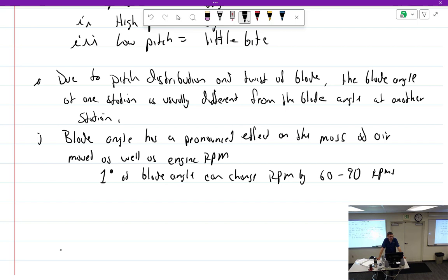It has to be in the chocks and blocked. So you'll actually look at the type certificate data sheet. That's where it's going to say it. It'll tell you what propellers belong on the airplane, because there's usually a combination and there's usually a range of blade angles that you can have for each propeller, usually by about 3 to 4 degrees. And they'll call it pitch though.